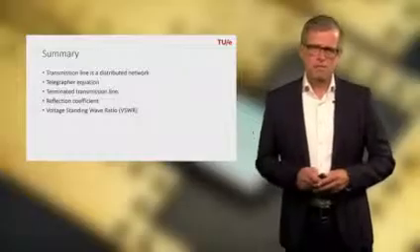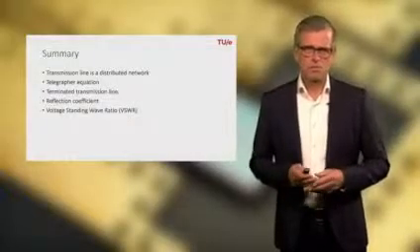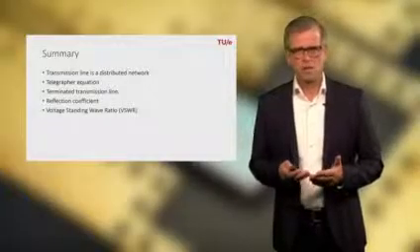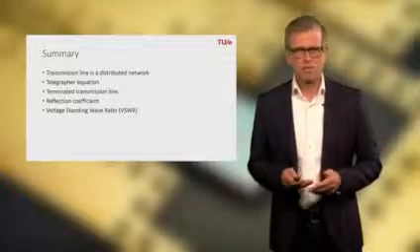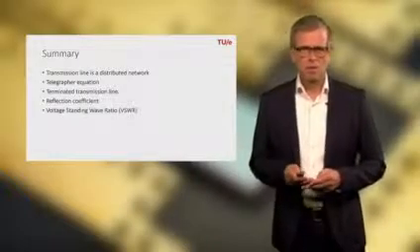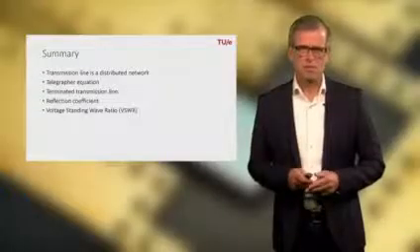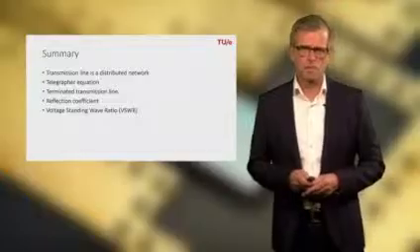So the summary of this third web lecture is that we have introduced transmission line, and we found a model in order to apply Kirchhoff's law. We solved the telegraph equation. We looked into an application of a terminated lossless transmission line. We found the reflection coefficient, and we introduced the voltage standing wave ratio.